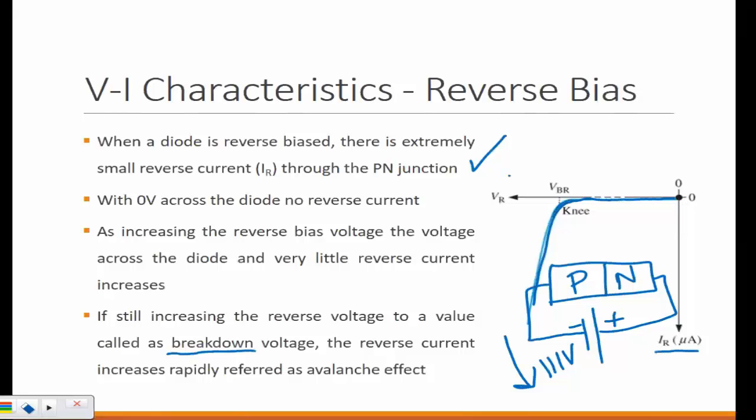Yeah, because you are measuring. If you use the meter in the same location as opposed to forward and reverse, if you don't flip the meter, you read a negative reading. So that's why it was plotted on the negative axis. So negative current, negative voltage. Right? So it's placement of the meter. If you don't reverse the meter, if you keep the meter in the same location, either in forward or reverse, you're effectively going to read negative voltage, negative current, right? Negative voltage. Yeah, current will be negative as well if you go the backward direction.